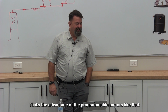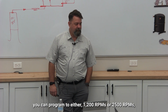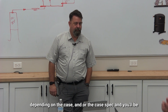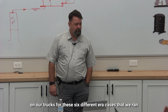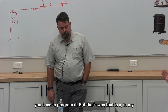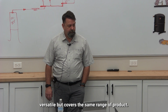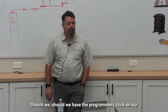That's the advantage of the programmable motors, though, is you have a fixed fan blade to a fixed motor that you can program to either 1200 RPMs or 2500 RPMs, depending on the case manufacturer or the case spec, and you'll be correct. Whereas we carried 6 different sized cannonballs on our trucks for these 6 different cases that we ran into. That's a lot of truck stock motors where we could have had one. You have to program it, but that's why that is, in my opinion, a better motor or better setup, because it's more versatile but covers the same range of problems. There are a couple of different sizes of those. Should we have the little programmer stick on our trucks like everybody? It depends on which motor you're gonna carry on your truck, right?